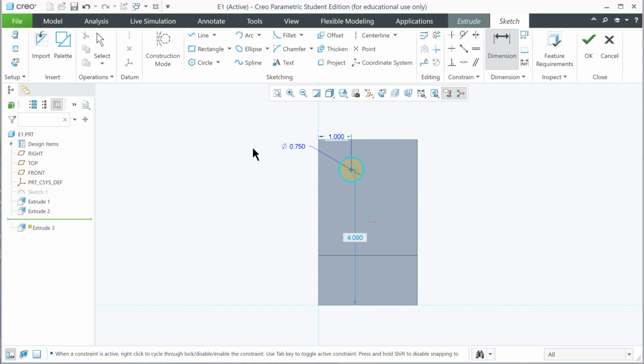Well, here's where Creo's rather interesting. Remember, Creo comes up from 1987 and it has a tremendous amount of technology built into it. The way it works is very different than what you see most things work today. They've improved upon that, and they've really made it very Windows-esque. But some things like this carry over. Here's the trick. Middle wheel click, and it will drop in the dimension. Sorry to be long-winded there, but anyway, go ahead and type in 1 and hit enter.